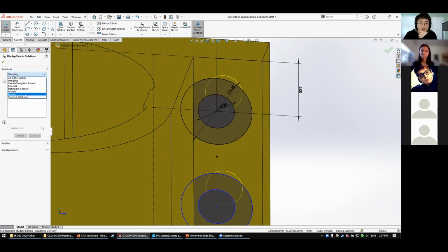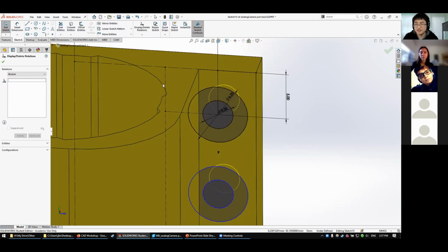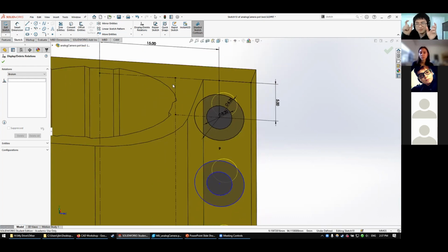There's also broken. When's the last time I saw a broken relation? Well, when it's broken, it's really broken, so you have to fix it or delete it. Broken usually occurs when both sides of the relation are dead, so it's like an orphan relation, I think. Or the relation is illegal. Like you can have two things that will define something, like a length. How to explain this? But broken: delete it, make it again, pretty much.